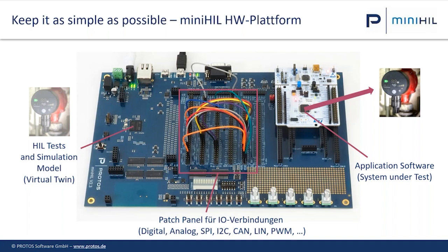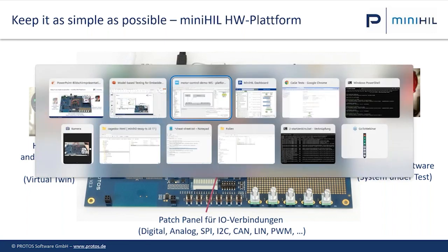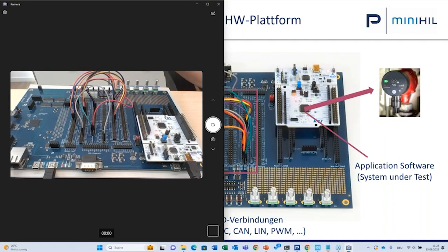That's a little hardware-in-the-loop test system that tests a microcontroller with a complete software. So it's the smallest possible hardware-in-the-loop test on your desktop. I have an example here. That's my setup. That's the system under test, an STM32 in this case, a microcontroller with a motor control software.